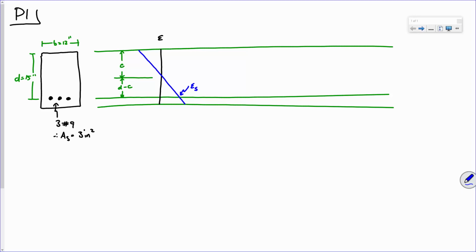The 0.85 was the width of that stress block. Remember, the maximum strain was 0.003. Y'all remember that? Remember, that's the maximum usable strain. You'll see an equation that we'll use here in a second. Oh, now I remember. Just bear with me.